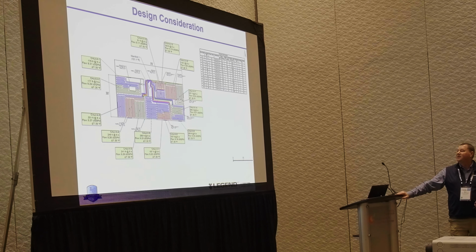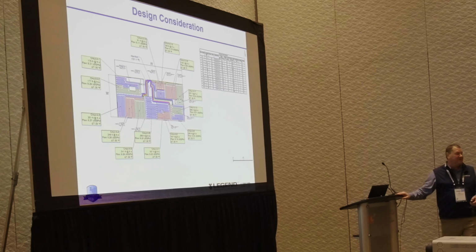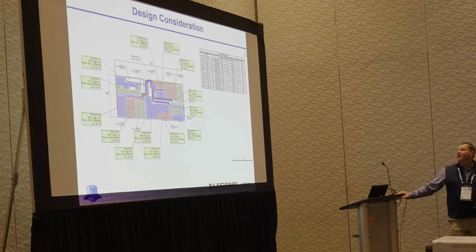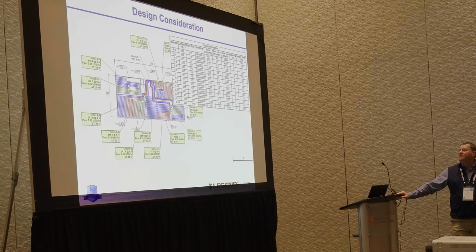But if I put remotely located manifolds, this is the same thing. I now have total control over every one of these rooms because these 3 loops can be zoned back to this manifold, these 2 to that one. But again, installing those tails is very difficult. This hallway is going to be cooking. This mechanical room is going to be cooking. Better control, but not a better design.